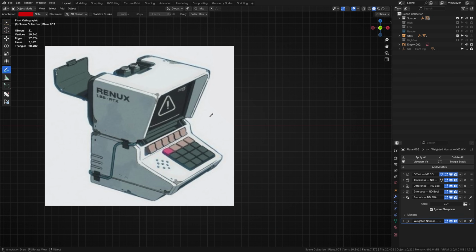Let's begin. I'll start with a simple detail, this grid of buttons. What's the first obvious way to reduce complexity here? It would be unrolling the arrays back to a single button. Great, now what's next? If I draw out what this button looks like from the top, we're greeted with a familiar shape. It's a cube with rounded edges. The answer should be clear at this point. To model this button, we'll need a plane. We'll then have to bevel its corners and extrude it.